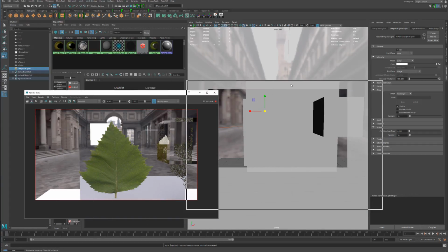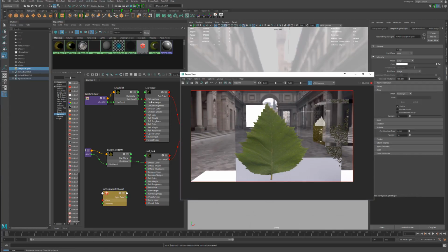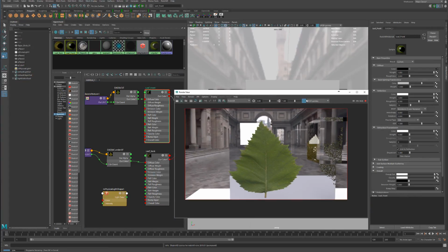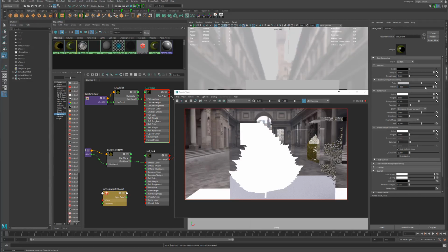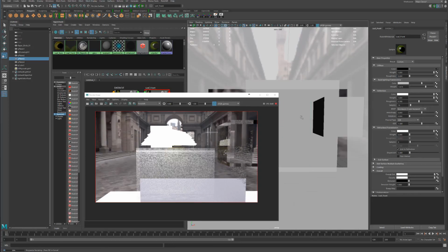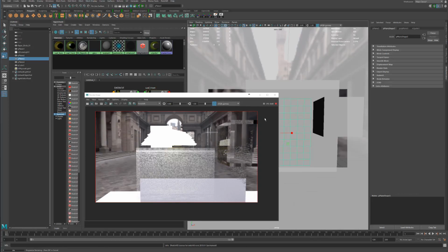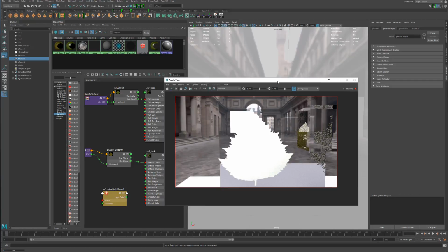And so to get that to happen, underneath the Redshift material, we actually have to turn on Backlighting Translucency. Right now, the weight is at 0. I usually stick with 0.5, but let's just go all the way to 1. Yeah, 1's way too much. And okay, see, we're getting this bug again. Let's hide that and unhide. For some reason, that seems to fix it.